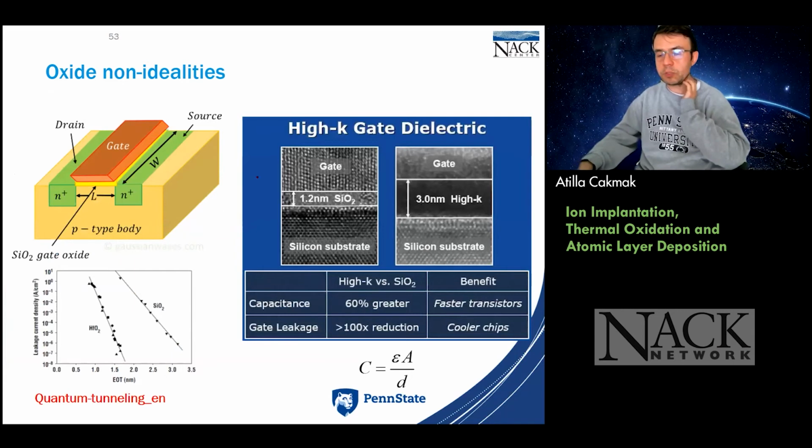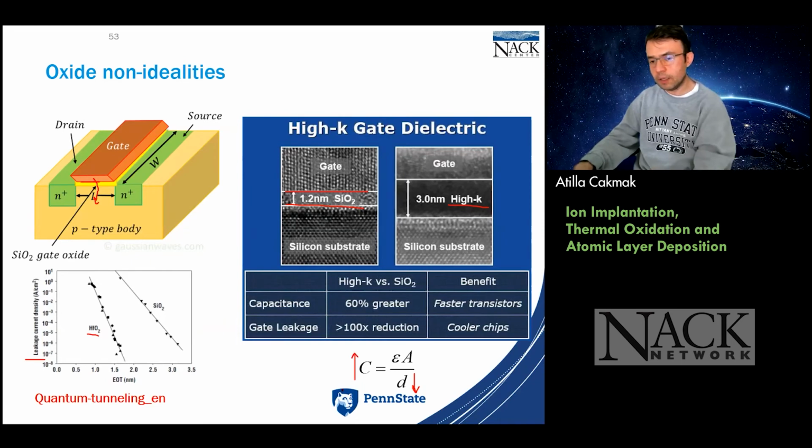So people switched to what I also showed you, high-K dielectric materials like hafnium dioxide. They use ALD, atomic layer deposition, for that. And this actually lowers the leakage current a lot. The leakage current, again, remember, is the current coming from the gate into the material here, because we're shrinking the thickness down to, say, 1.2 nanometers. While we're shrinking down the thickness d here, we're actually getting an elevated capacitance during the shrinkage.